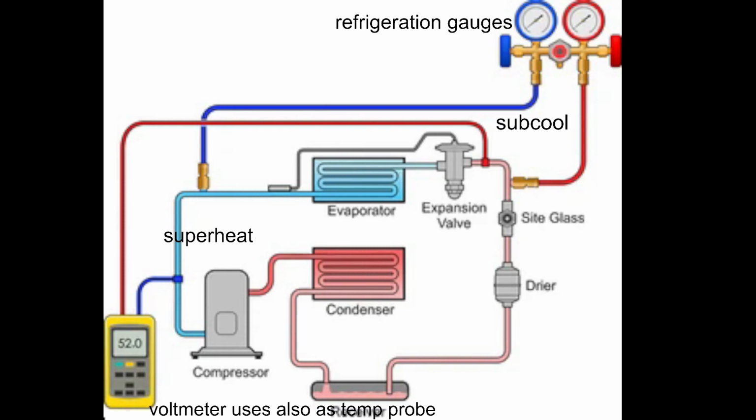So as you go on, you'll see where it's connected to your meter. It goes to the expansion valve, goes to the evaporator, goes over and then back into the compressor. So your evaporator is the one that's inside your home. If you have a home and your AC system is in the hallway, that's called an upflow. If you open it up, the top part, all you got to do is find the copper lines, the two refrigeration lines. One is smaller, one is larger. One is high side, one is low side.